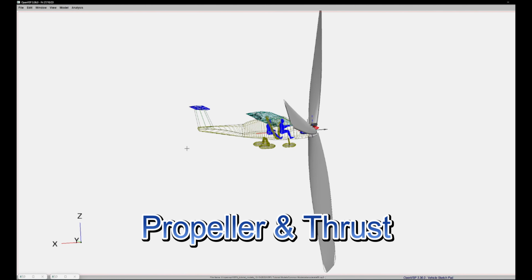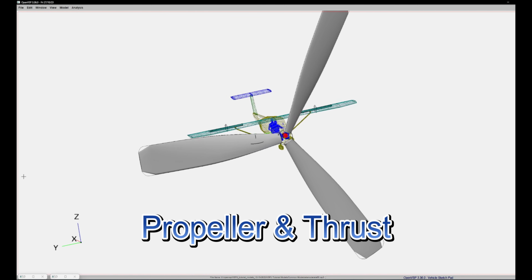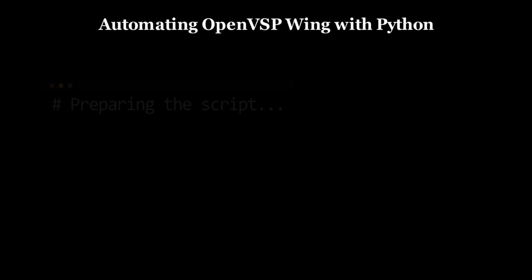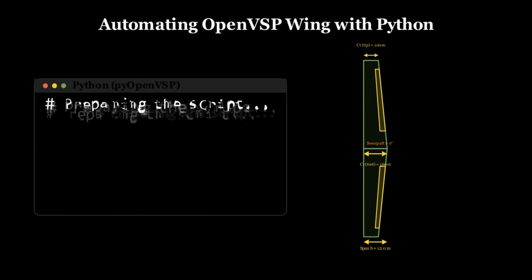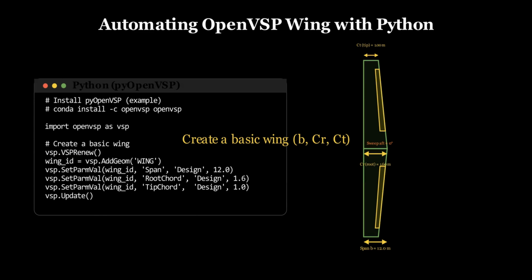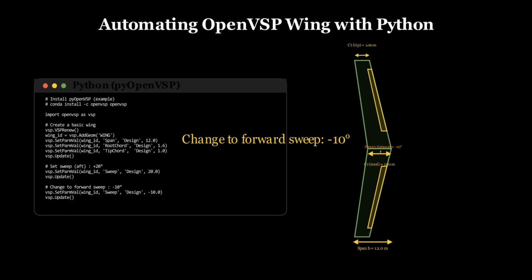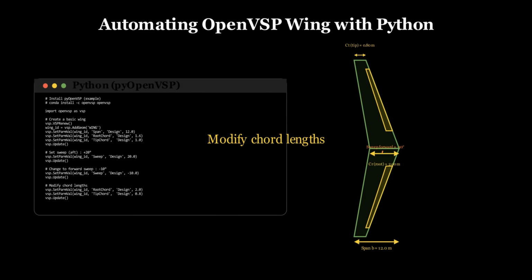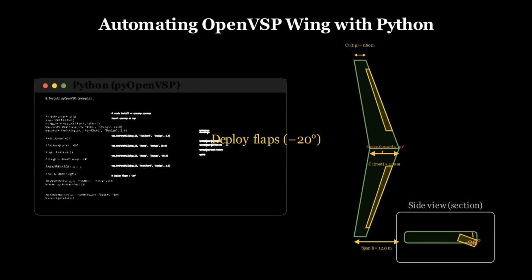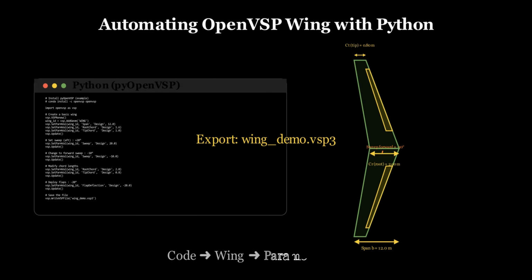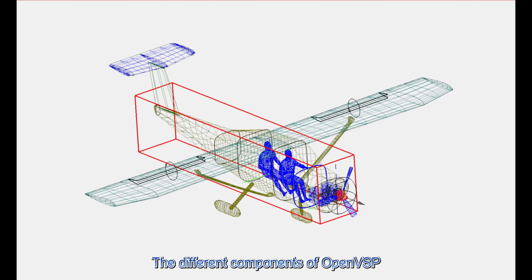After completing the stability calculations, I further advanced the aircraft's propulsion system analysis using OpenVSP. Compared to traditional CFD systems, OpenVSP offers a modular modeling approach and connects with Python in a very fast and efficient way. In OpenVSP, the aircraft is modeled while retaining the configuration information from previous calculations.